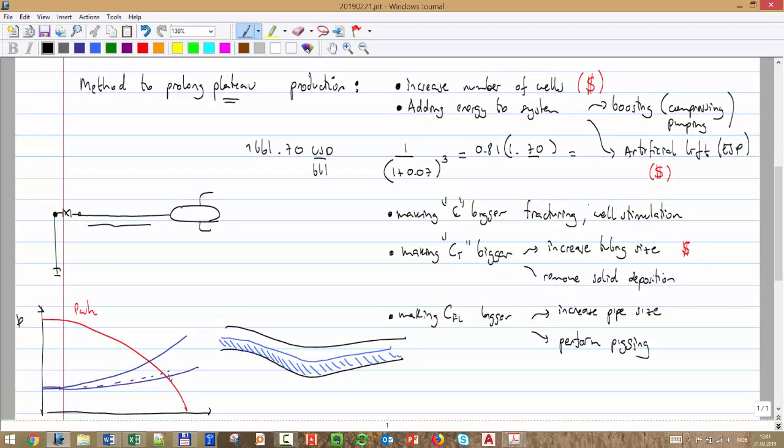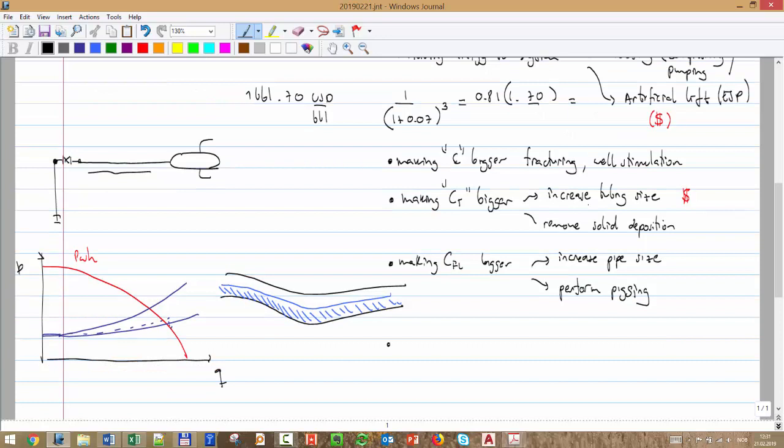Decrease pressure in the separator. We don't like it too much. Okay, process engineers don't like it at all. But remember, we have two pressure bounds. One, we cannot control much. We are draining and that's going down. Well, maybe we can control a bit. But the other is the separator, and if we lower that, we are going to get more production. So decrease P separator. But here we have to be careful with the angry process engineer, and we have to be careful with processing requirements.